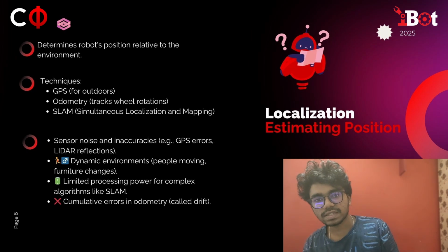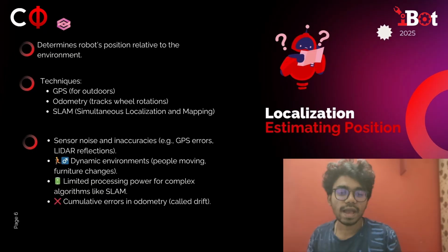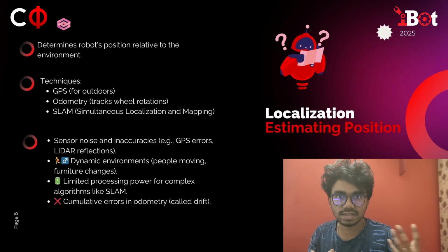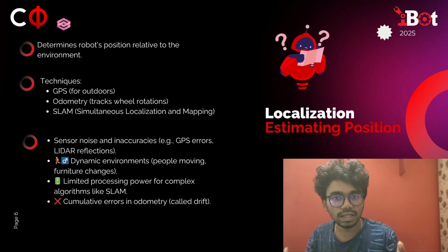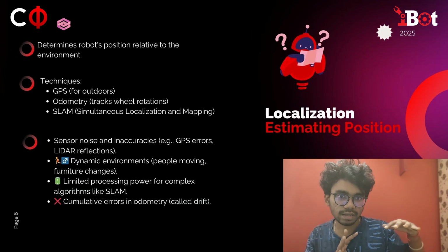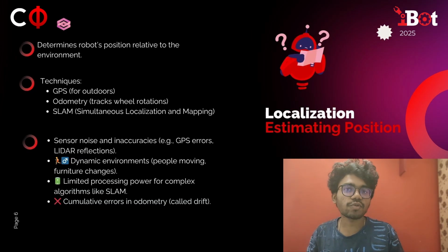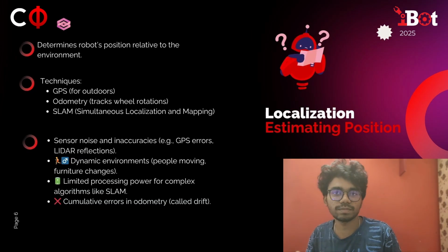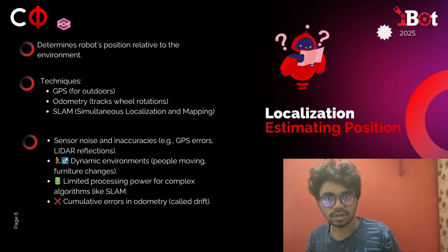So we need to also build a system which accounts for the fact of these dynamic objects, and it detects that yes, this sensor reading or this data which I'm getting is very different from all the three data. So this must be a dynamic object, and it should treat it as dynamic, or basically neglect that certain information from that sensor for now. Or it might be from a faulty sensor. Basically, suddenly the robot might think the sensor has a fault or something. So this detection should also be taken into account and fed into localization basically.